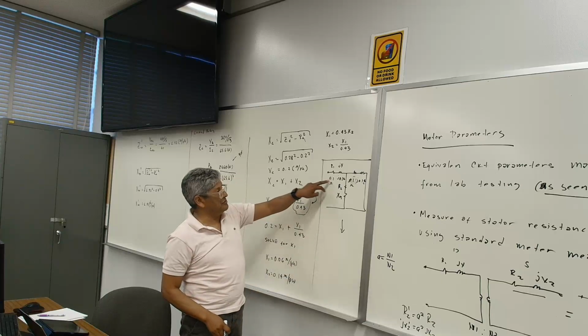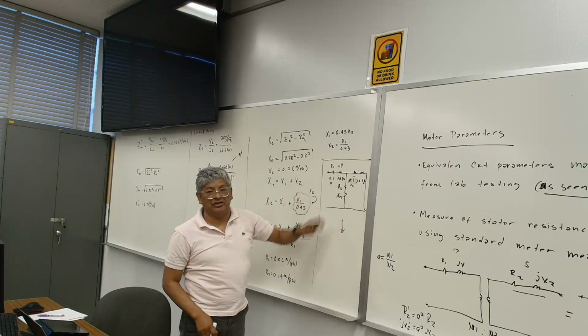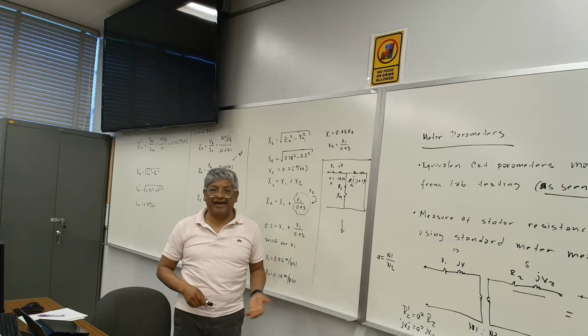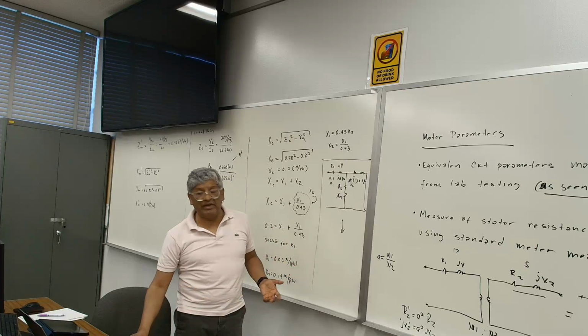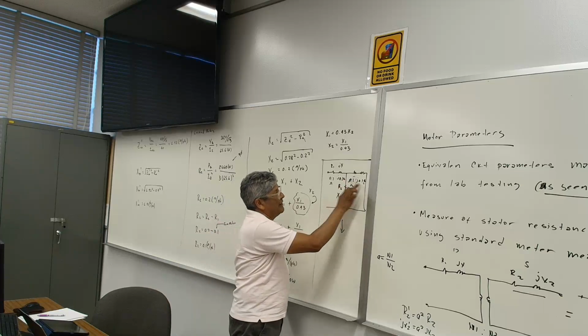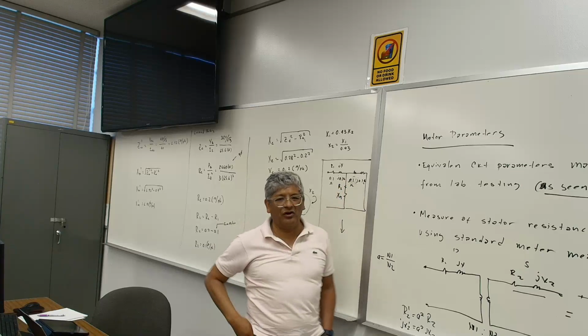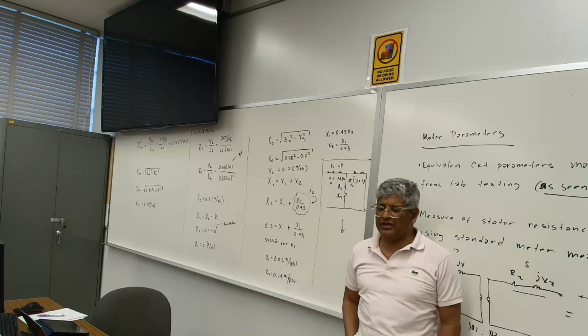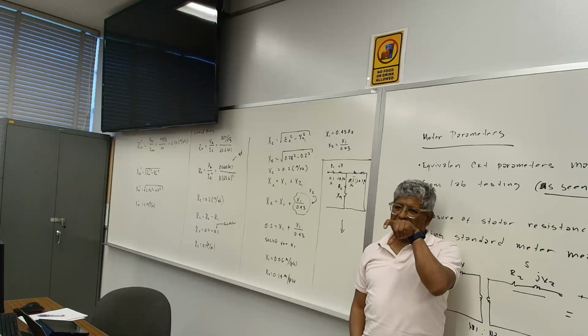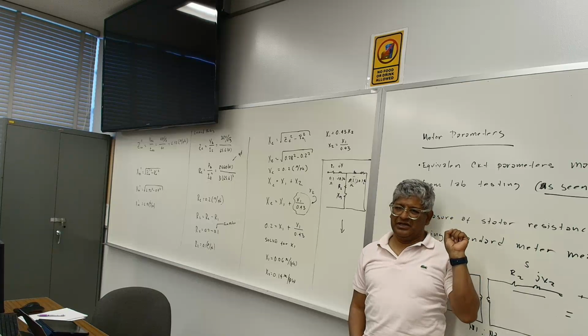Now I have values that I can enter into my computer model, or if I'm doing it by hand. So that's basically what we did. There's one little thing here. These numbers are all off, and I'll talk to you guys about it when we're doing the simulation. The reason is that when you're doing the measurements, the frequency inside the rotor is 1/4 of the actual frequency.